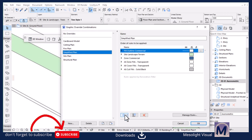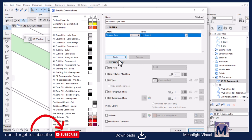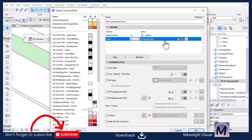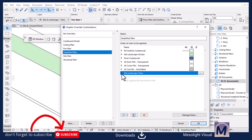So again we need to set a rule, let's say manage a rule for the trees. I'll say site landscape trees, enter. Then this is going to be what? Object. And yes, we just set that. It's going to be an object. Then hit OK. Now let's add a layer because it's an object that is under layer site trees. And hit OK. Let's add that rule. Hit there. Move it to the top.